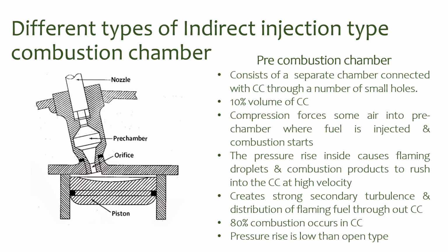This will create strong secondary turbulence and the distribution of flaming fuel throughout the combustion chamber. 80% of the combustion occurs in this combustion chamber. Pressure rise is low compared to an open type combustion chamber.